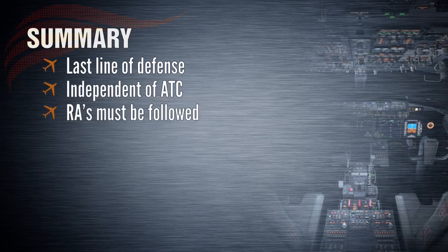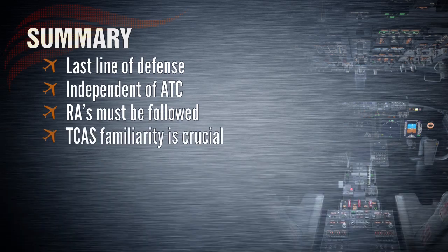Resolution advisories must be followed, even if you think you have the traffic in sight. The traffic you see may not be the traffic that the RA is maneuvering you to avoid. Familiarity with the various TCAS advisories is crucial. TCAS expects a response within 5 seconds of initial resolution advisory and within 2.5 seconds of a resolution advisory reversal. This is not enough time to mull over what you should be doing.